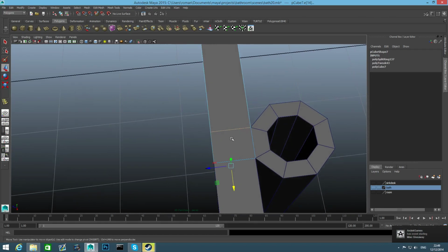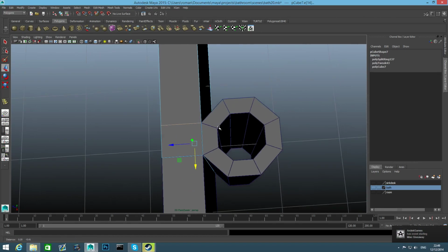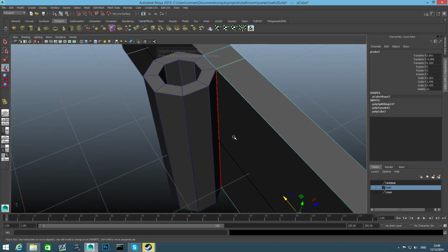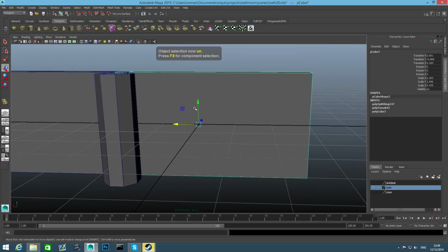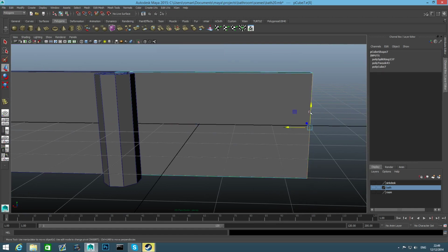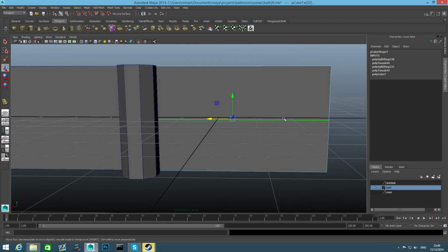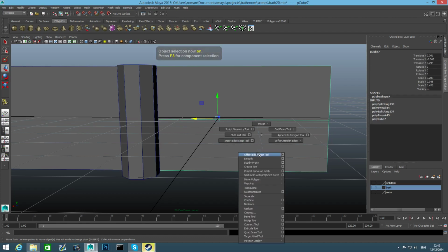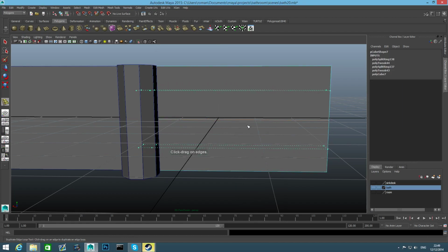Okay. So now what I want to do is attach this cylinder into this area. So as it is, I'm going to press F8 first, then right click, choose edge, grab this edge, control right click, edge ring utilities, to edge ring and split. That's good. And press F8 to bring it back to object mode. Shift right click, offset edge loop. I'm going to add edge loops.